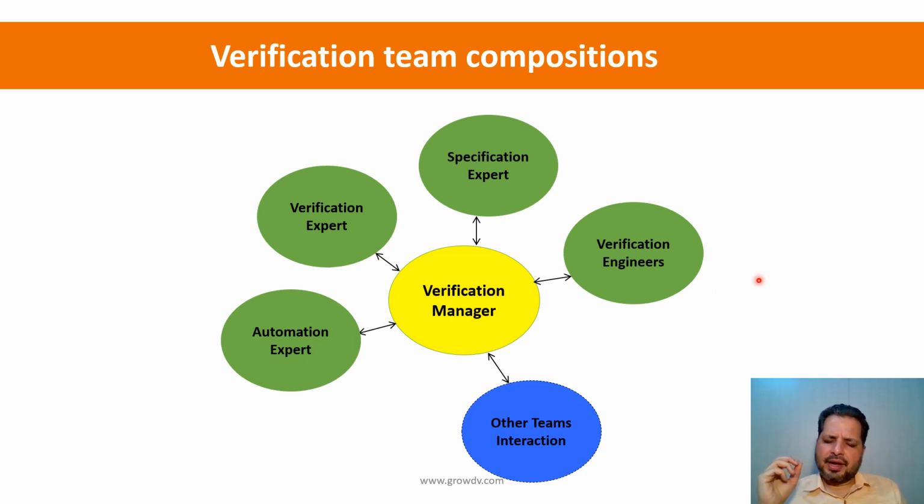And when they are asked to implement a particular component, let's say an agent or a scoreboard, they understand what that means, and they also understand how to run the tests around them, and if something is failing, go through the debug process to isolate the issue. If there's a test bench issue, fix it. So that is the expectation from the verification engineer.